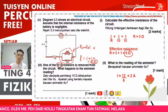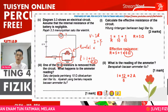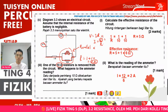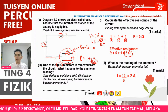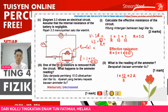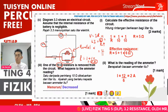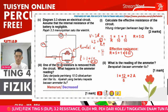Or you can use V equal to IR, so I equal to V over R. You can see the voltage here is maintained at 12, with the value of R increasing from 6 to 11, so the current flow will decrease. So it is very clear that the ammeter reading will decrease. And you can actually calculate the answer. The current flow now will be 12 over 11. So you have to change it to decimal places for your final answer, if the question asks about this.